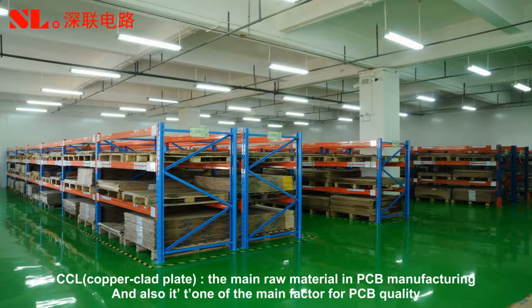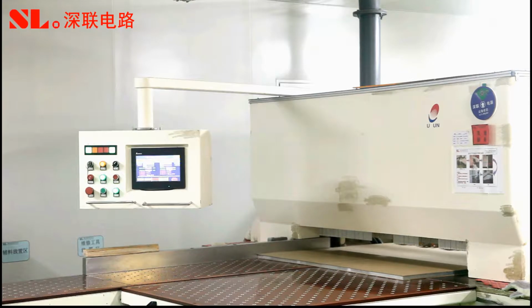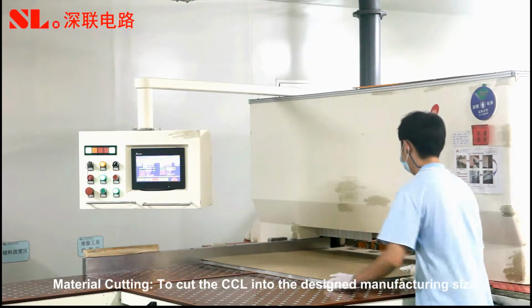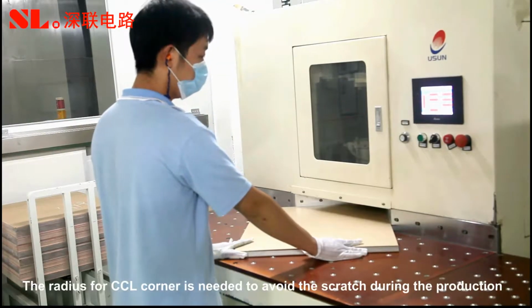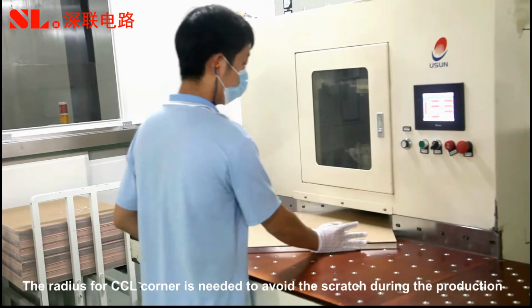Copper-clad laminate. It's the main raw material in PCB manufacturing and also one of the main factors for PCB quality. Material cutting. To cut the CCL into the designed manufacturing size. The radius for CCL corner is needed to avoid the scratch during production.